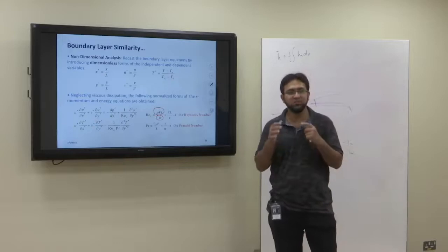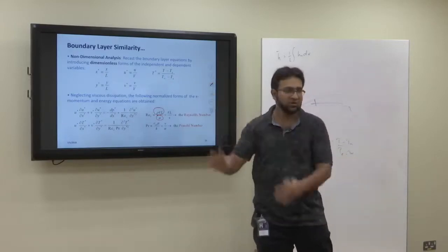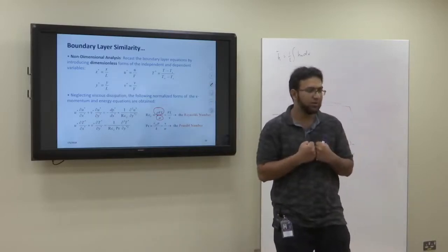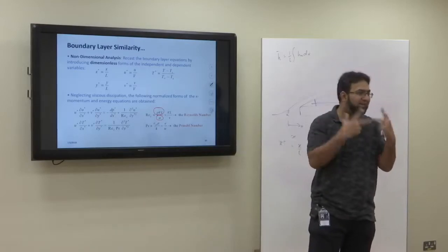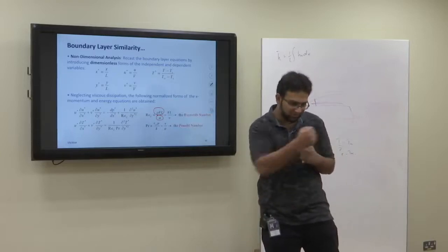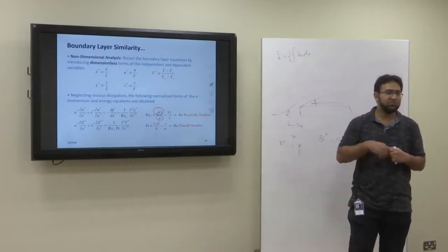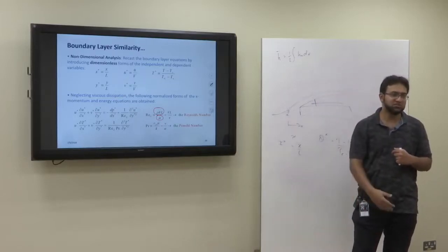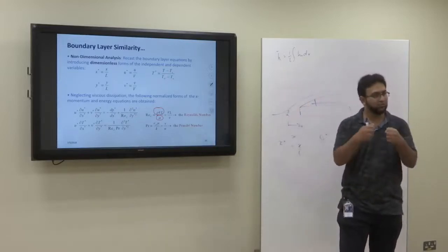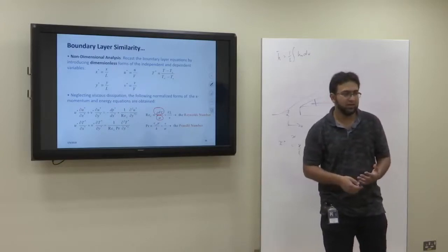So in physical terms, what does Reynolds number mean? We have the inertia force. Inertia force tends to make a fluid keep on continuing to move forward. Viscous force, it's resistance between layers, it tends to stop the fluid. So there are two forces fighting. One force is trying to make the fluid move forward, the other force is fighting to stop the fluid motion, okay? So if the inertia force is high, the fluid will be moving very quickly. If the viscous forces are high, then the fluid will be moving slowly. Okay, and that determines the smoothness of the fluid flow.